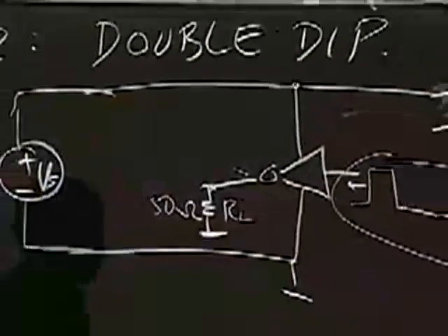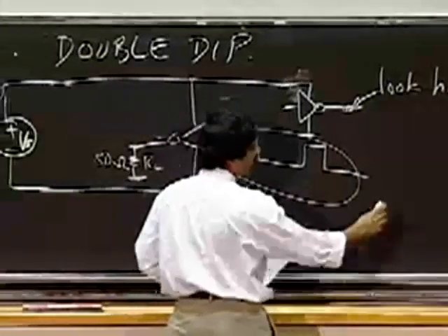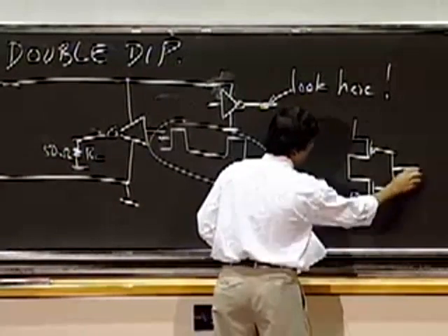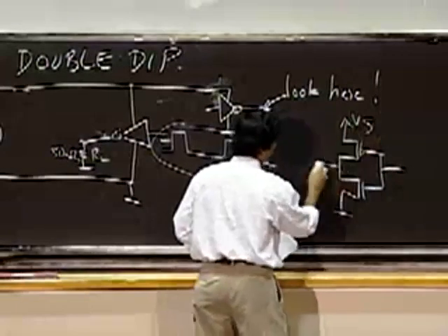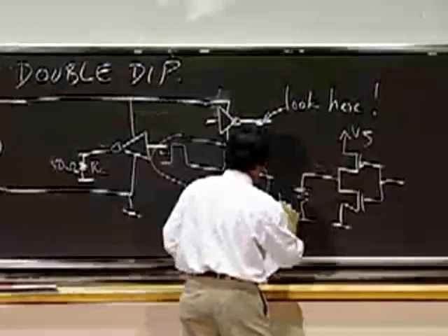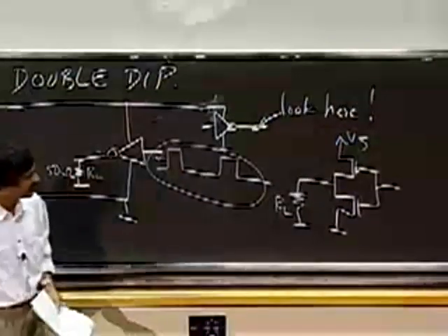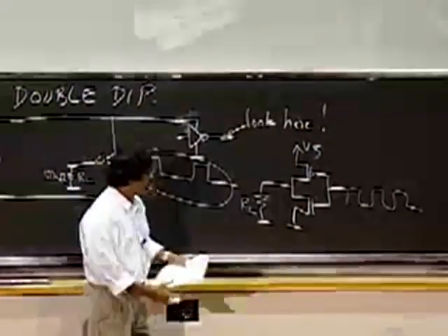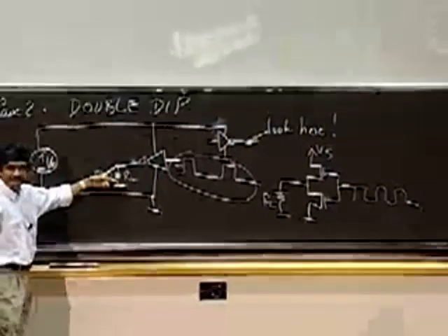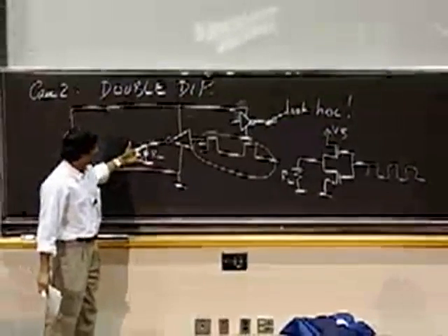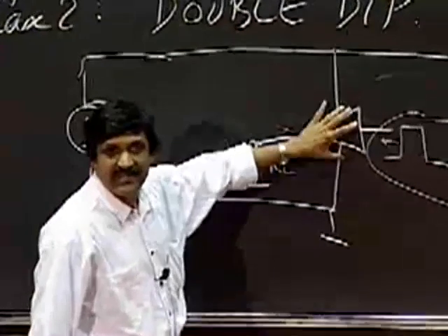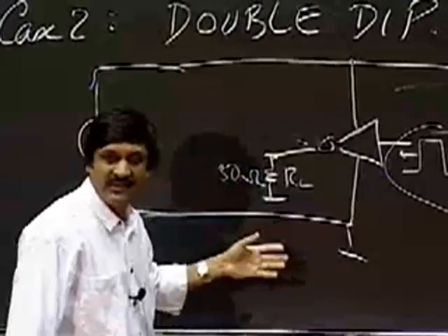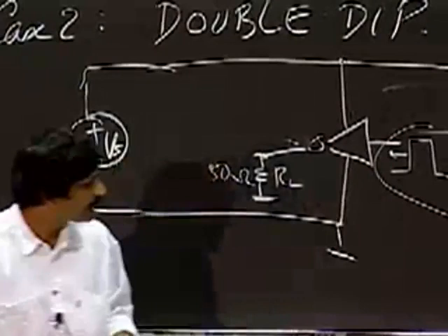And this inverter here, I believe, is a CMOS inverter that looks like this. Okay? So I have this input applied to this inverter, and all I did is applied an RL load here. I noticed that the load here should not really change what's happening if this is an ideal inverter. Okay, the load here should simply draw some current, but really should not change any other property.